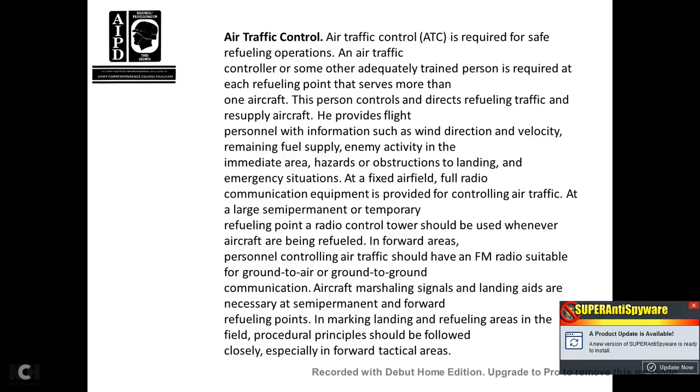Air Traffic Control, ATC. Air Traffic Control is required for safe refueling operations. Air Traffic Control or some other adequately trained personnel are required at each of the refueling points that serve more than one aircraft. The person controls and directs the refueling traffic and the resupply of the aircraft. It provides the flight personnel with information such as wind direction, velocity, remaining fuel supply, enemy activity, areas that have obstructions, landing emergency situations, and airfield status.